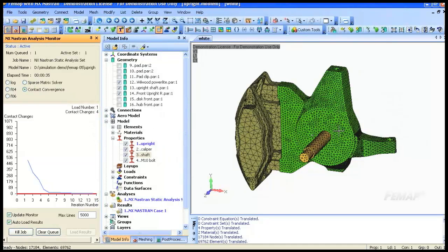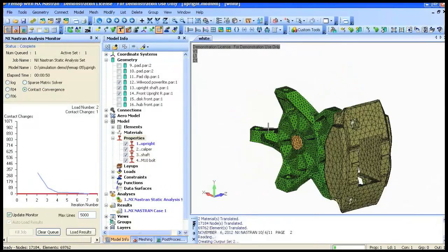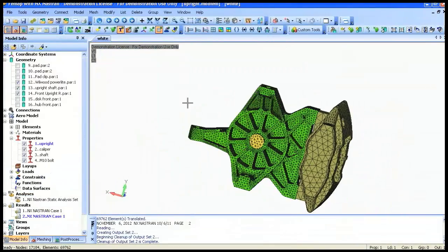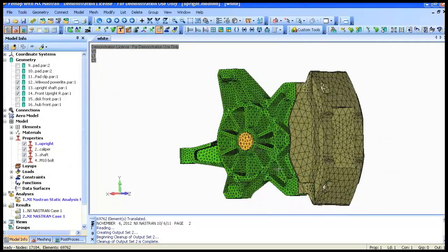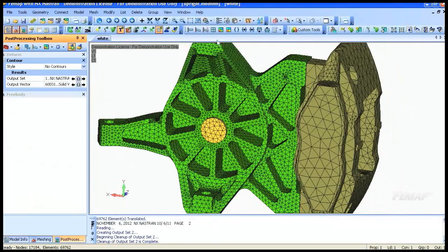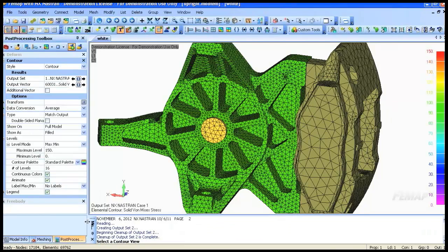So it's actually an iterative process because it doesn't actually know how far to shrink the bolt. It has to do it over an iterative process. In this particular example, it takes 2 attempts to get the correct preload in the bolt, just basically by some kind of shrinkage being applied to it. So we can just run through the analysis again. And just again, like so.